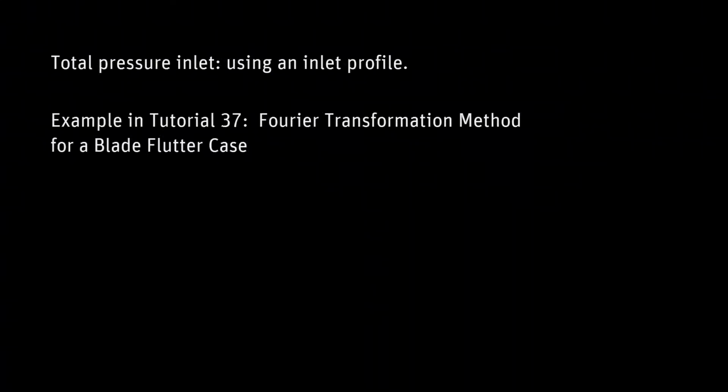I've applied a total pressure profile at the inlet. More detail on how to apply a profile boundary condition is shown in tutorial 37 of the CFX documentation. I'm also using a static pressure outlet of 138 kPa, utilizing radial equilibrium pressure averaging.